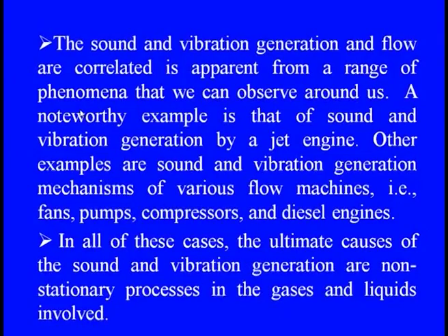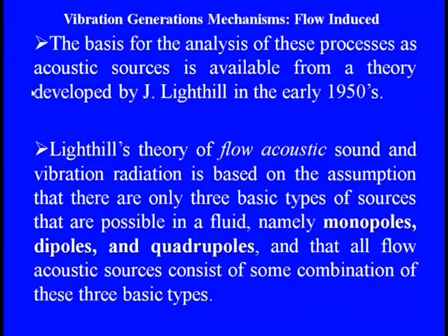So, these cases ultimately cause a huge amount of vibration and sound generation, but the waves or signals being generated are categorized under non-stationary processes. This is one of the significant criteria when we are trying to measure those things. We need to analyze based on this non-stationary feature of the generations, irrespective of whether in gases or in liquids. So the basis of the analysis is that they have non-stationary features.